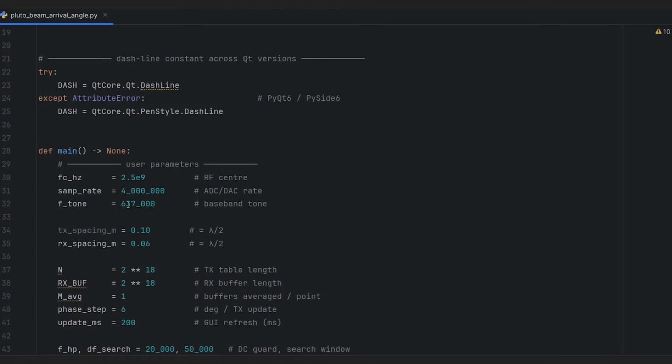Because if we don't create the sine in the baseband, our bandpass filter after the baseband will filter out any DC information. And that filter is actually essential because we need to clean the signal after the output of the digital to analog converter, or before it goes inside the ADC in the receiver.